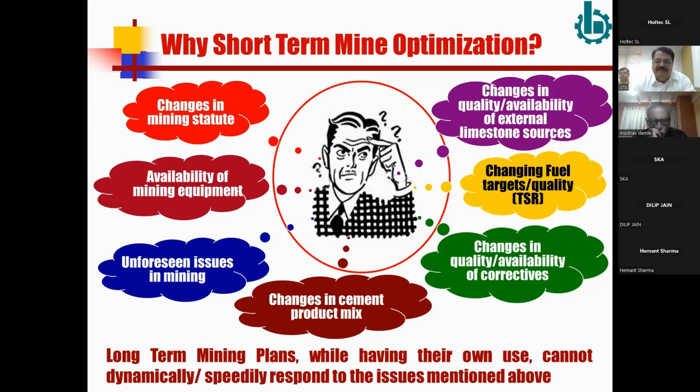The change in the demand of ROM quality of limestone may be due to the plant side, or maybe it can be from the mine side. Many companies globally are manufacturing different types of cement, like OPC, PPC, PSC, SRC, or OWC. For OPC, PPC, and PSC, there is no requirement of changing the ROM requirement because the same clinker can be used for producing the cement.